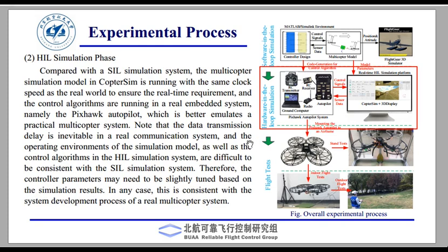Detailed steps are here. Okay, compared with the software in the loop simulation system, the multi-copter simulation model in CopterSim is running with the same clock speed as the real world to ensure the real-time requirements, and the control algorithms are running in a real embedded system, namely the Pixhawk autopilot, which better emulates a practical multi-copter system.